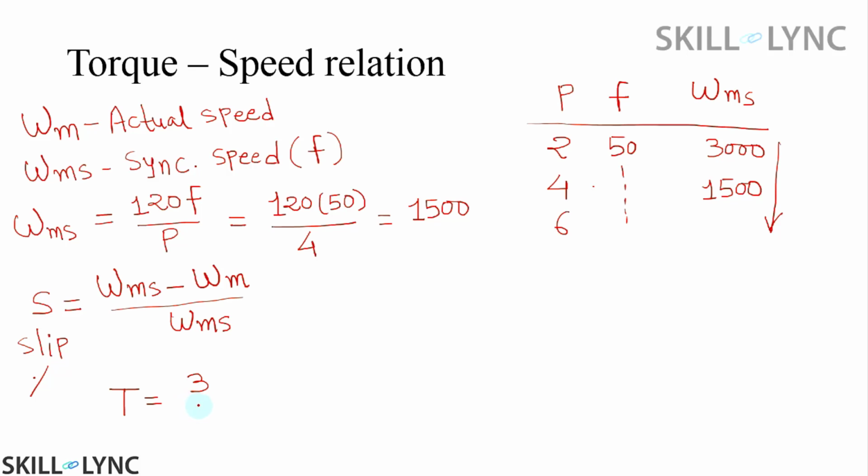Directly writing this equation in order to move ahead quickly with electric vehicle application. So I'm not going to derive this equation, we are going to understand this equation only. So this equation is written as 3 divided by omega ms, which is the synchronous speed, times a factor which is dependent on the voltage. This is the per phase voltage applied to the stator of the induction motor, into a parameter called R2 dash divided